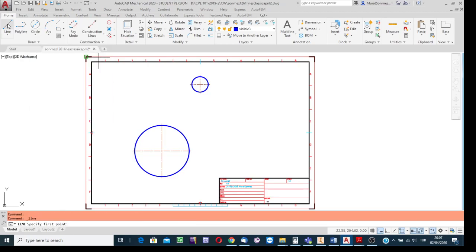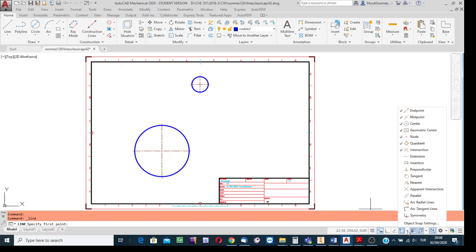First, start the line drawing process. And then, after starting the line drawing process, this is important, there is a must. You must change the snap enabling configuration. Bring the cursor onto this listing arrow, drop the list, and deselect, deselect, deselect. Only enable the software for indicating tangent points, or for enabling the tangent points to snap the cursor.